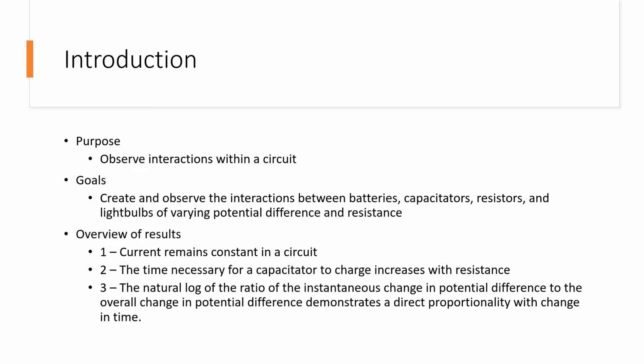In experiment 2, we found that the time necessary for a capacitor to charge increases with resistance. And then for 3, the natural log of the ratio of instantaneous change in potential difference to the overall change in potential difference will demonstrate a direct proportionality with change in time.